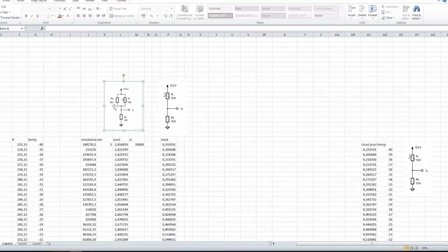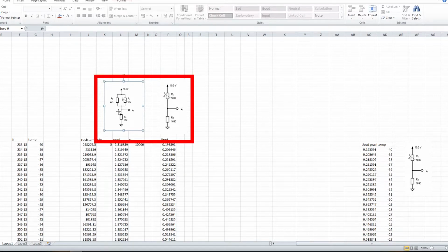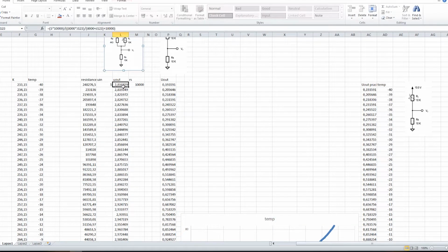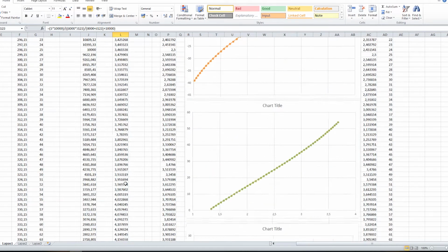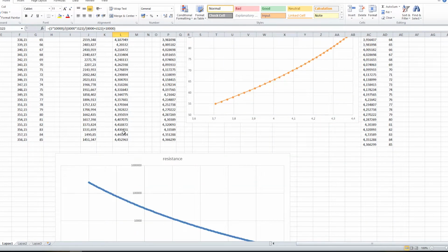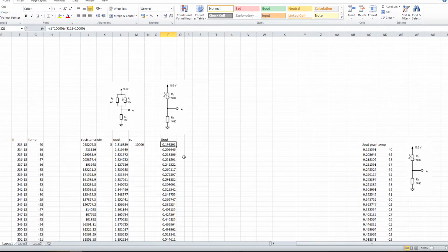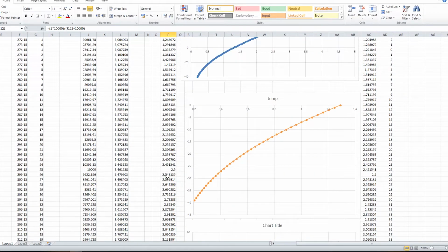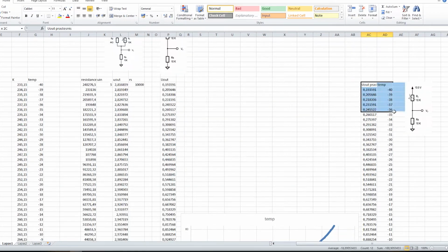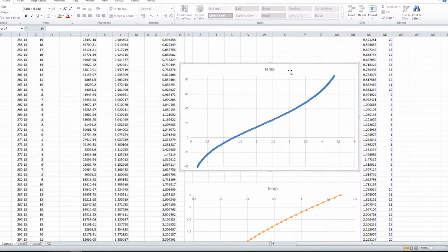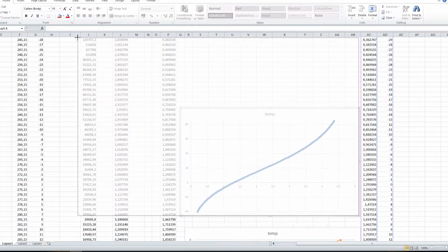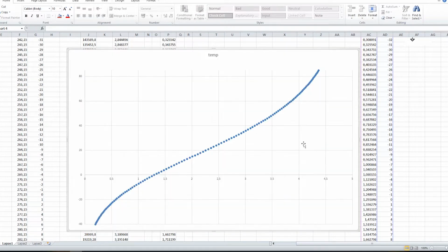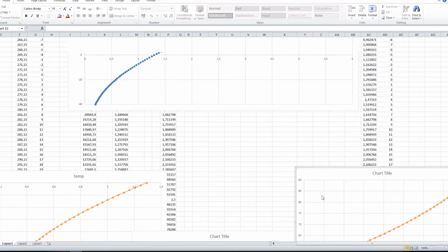There are two voltage divider circuits, which can straighten out the dependence curve. The first one straightens out better, however, the voltage range is much smaller. The second one suits me better because I will use a 10-bit ADC with which I cannot capture very small voltage fluctuations. So here we have an output voltage on temperature dependence graph. We can disperse this graph into 3 parts for easier formulas.